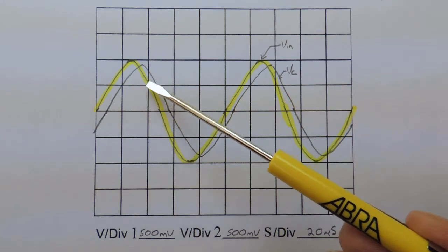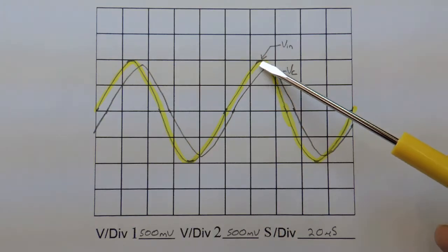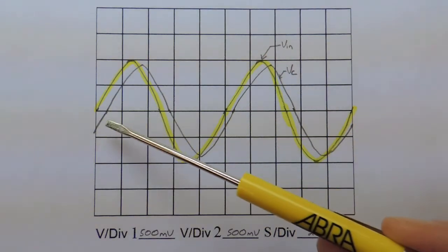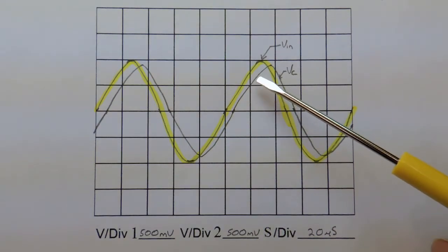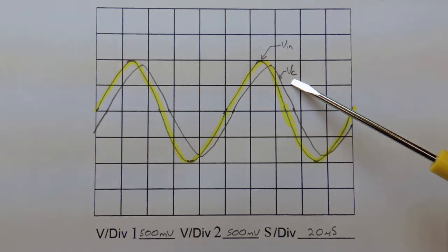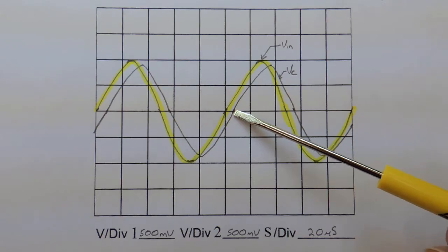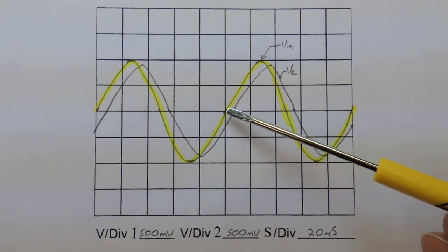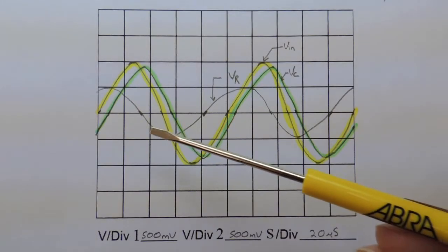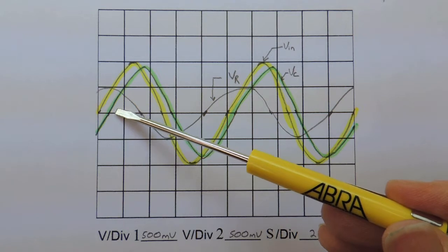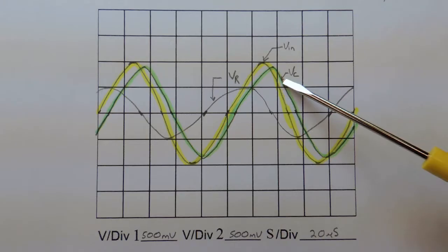So I've now highlighted my channel 1 waveform, and that was Vin, and I've sketched in my channel 2 waveform, and channel 2 is the voltage drop across the capacitor, so I labeled it VC, and you'll notice that I've drawn it in showing that it is actually lagging the input waveform. So I've now highlighted my channel 2 waveform with the green highlighter, and it is VC.